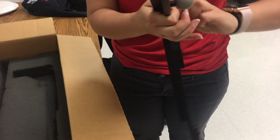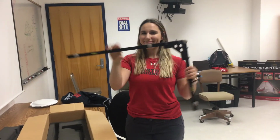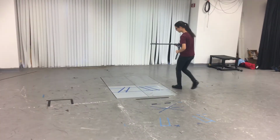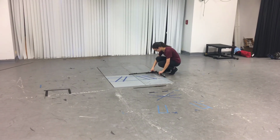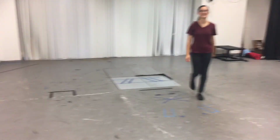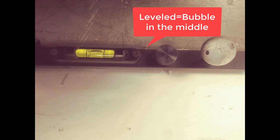Once you finish building it, you are going to place it on the force plates. Every lab is different, so the L-frame might look a little different in terms of the position depending on the lab. But basically what the L-frame is for, it sets the origin and the axes. Make sure to check that it is leveled.